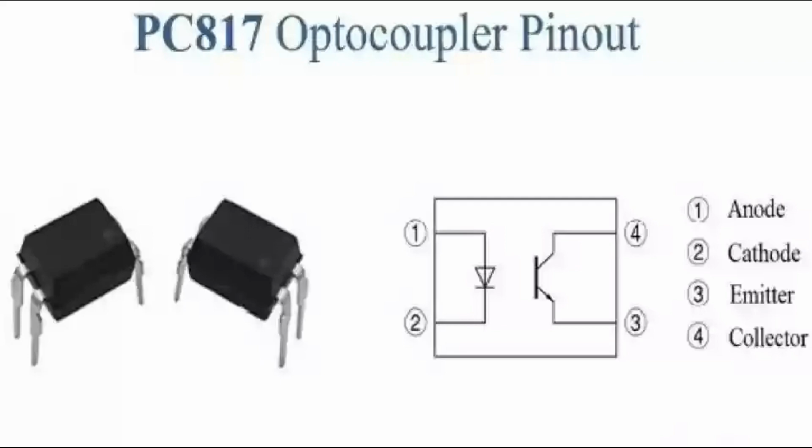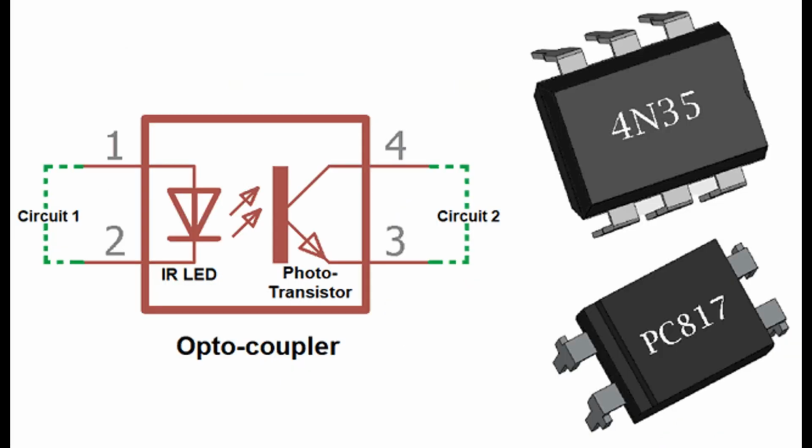Isolation techniques. Optical isolation, achieved through optocouplers or transformers, can physically separate noisy and sensitive parts of a circuit, preventing noise from transferring between them. Noise cancellation. In some cases, noise can be actively cancelled out by generating an antiphase signal, equal in magnitude but opposite in phase, and adding it to the noisy signal. This technique is known as noise cancellation.